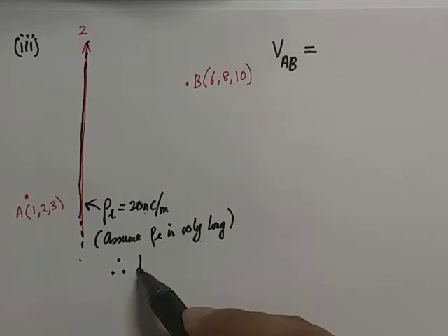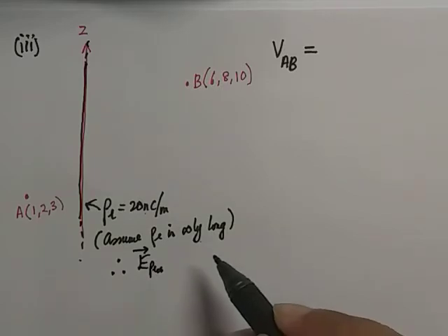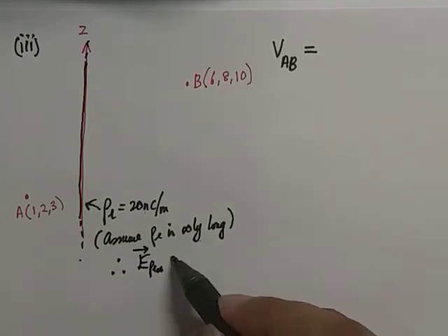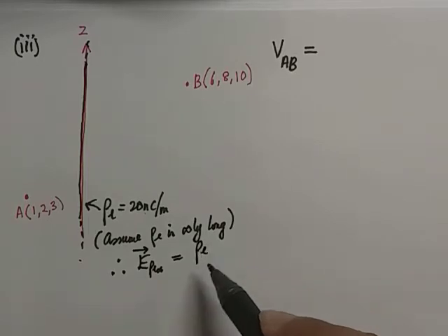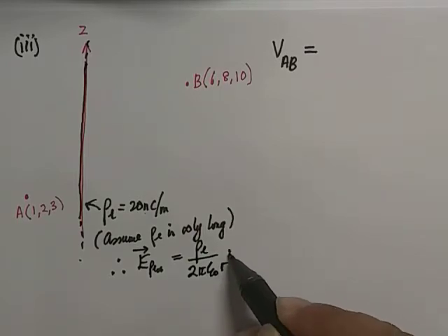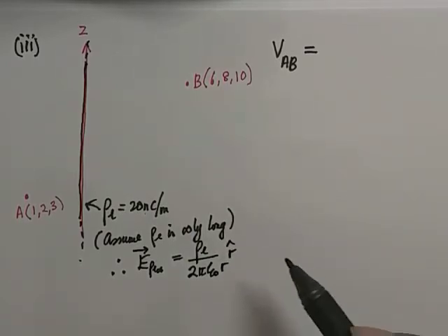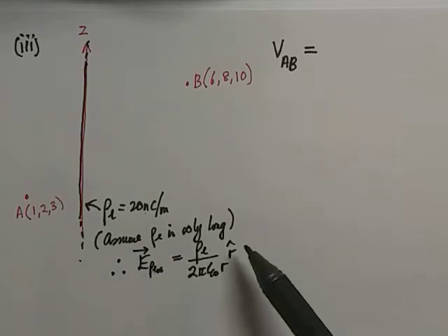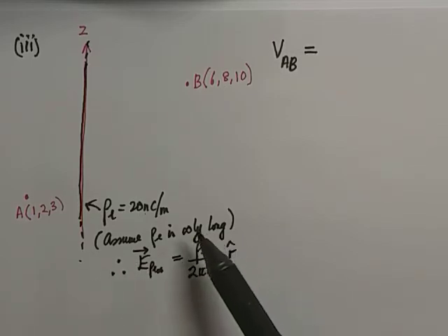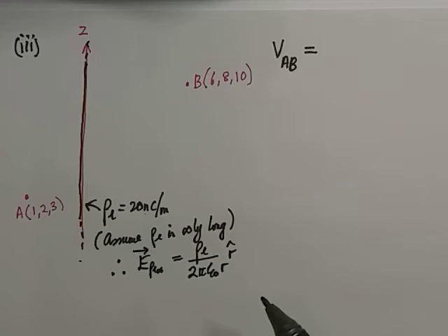So now the E for rho L infinity, remember the one we did together in Coulomb's law, is equal to rho L over 2 pi epsilon naught R in the R direction. We have seen this solution, and this solution refers to which coordinate? Yes, cylindrical coordinates. And we use epsilon naught here because the medium stated in this problem is free space. So this should be our standard solution.